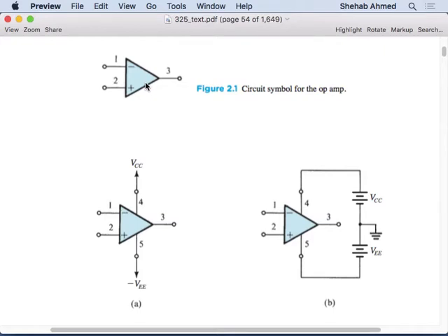And it's the same thing with an ideal op-amp. Of course, a real op-amp is not that way. A real op-amp will have a limit with respect to frequency. Why? Because it's a physical device. Any physical device you build will have resistors and capacitors that will create losses due to resistors, and will create frequency dependence due to the capacitance that you have, even if it's a parasitic capacitance, not the capacitance that you've designed and built in there.